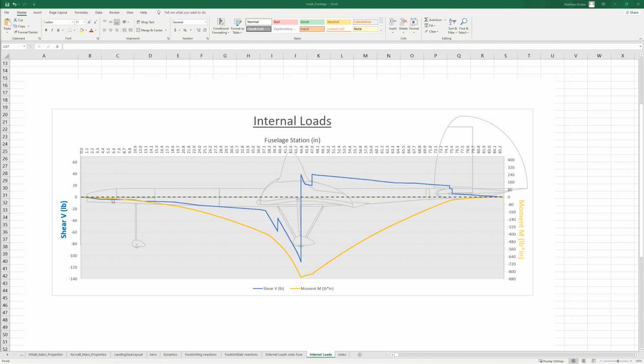And often, if there are points along it, you might label them for what maneuver produces that maximum moment. For instance, here it might be because of the 1.1G flare to 2G 2-point landing, and maybe a 3-point landing would be less here. So you'd label this as the 2-point landing, and then here the moment for a 3-point landing might be more, so here would be labeled with the 3-point landing.